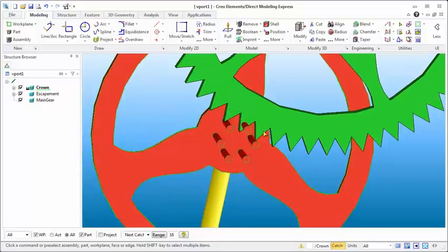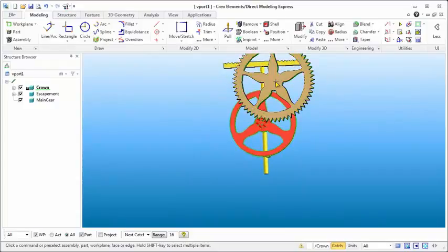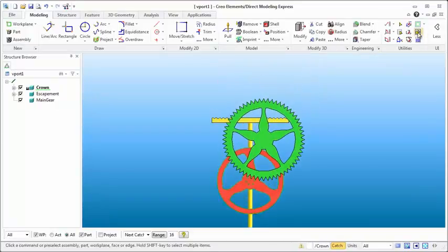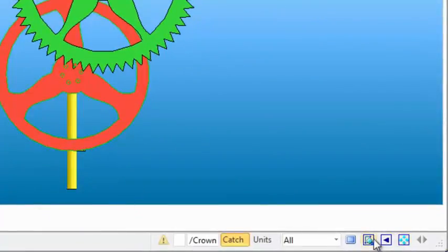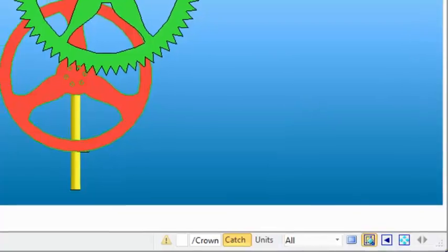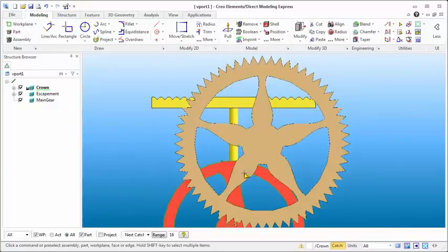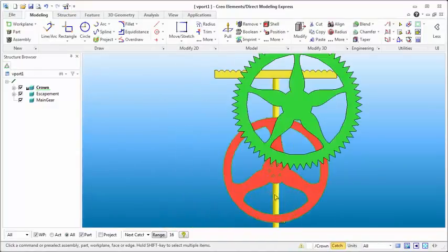So the next thing that we're going to need to do is I want to make sure that things are going to work out properly as far as the meshing of the gears. So I can choose on this face here, and one thing you'll notice is if you come up to here, there's this button that says view by that one face. And once you do that, you can also hit this, which will zoom everything into view, or you can choose this button here, and what it will do is allow you to zoom into one very specific spot like that. So you can start coming in and taking a look at things the way you really want to without necessarily having to deal with the scroll wheel, which sometimes doesn't seem to be doing what you really want it to.